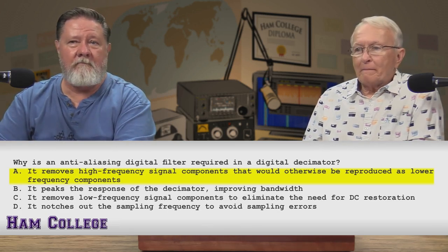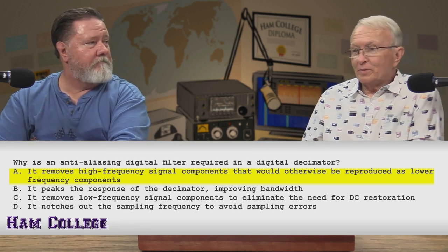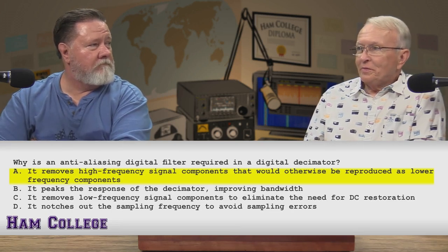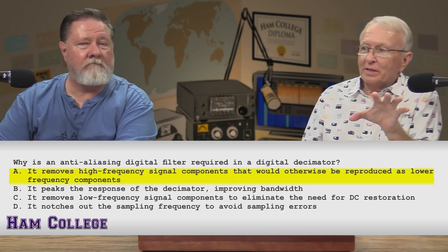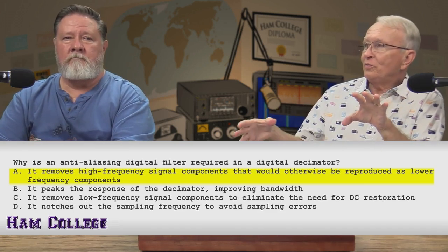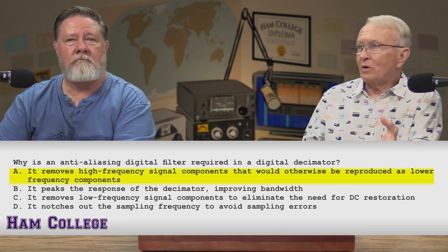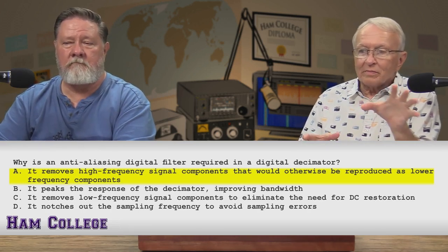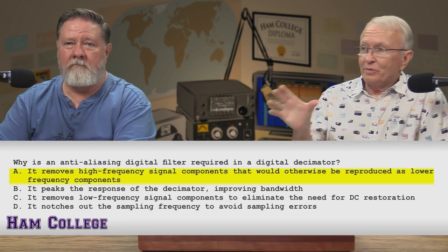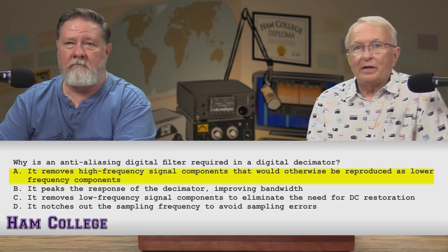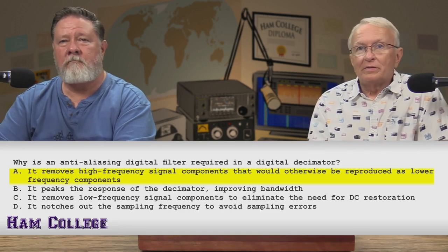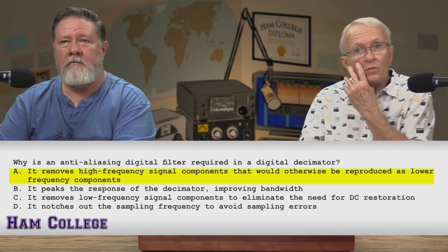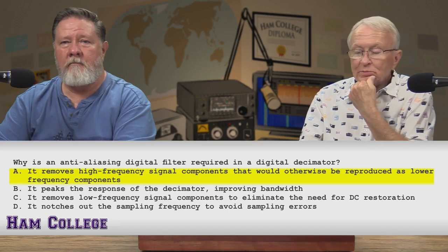It's sort of like, I'm not even going to get into it, but image signals on a receiver. If you've got a real strong signal, you might have an image a little bit off frequency from there that's generated because the strong signal is hitting your front end so hard that you've got an alias of your original signal as an image down there, and you need to filter that out. Same difference. That would be an analog example, more or less.